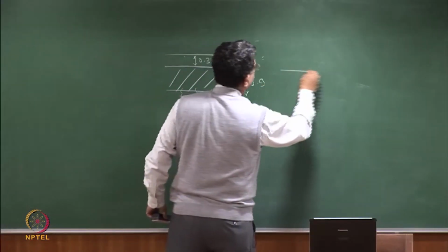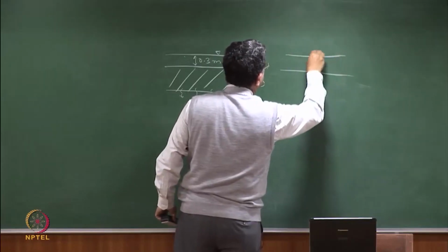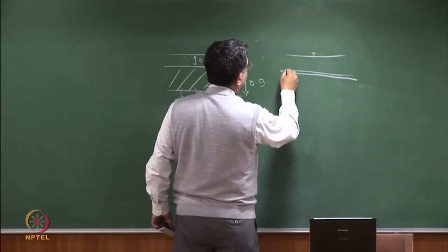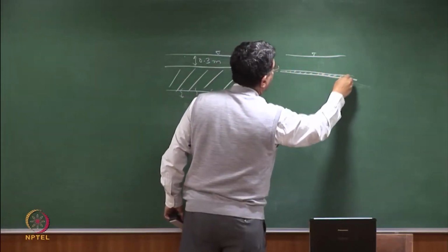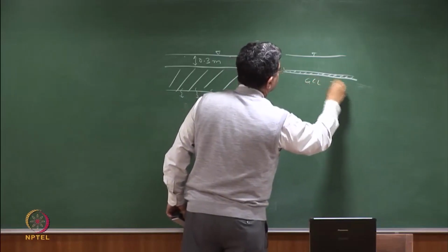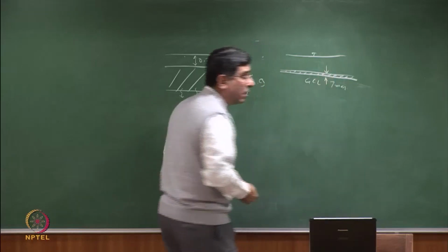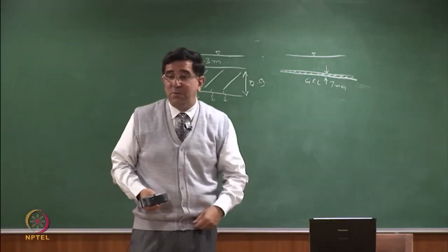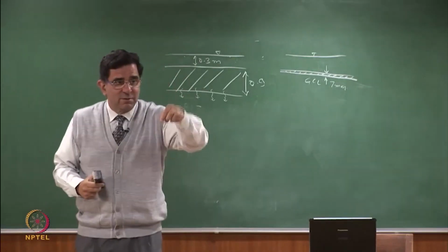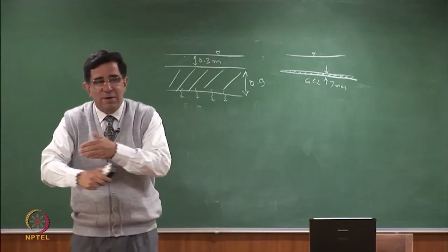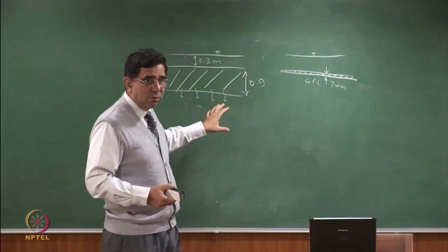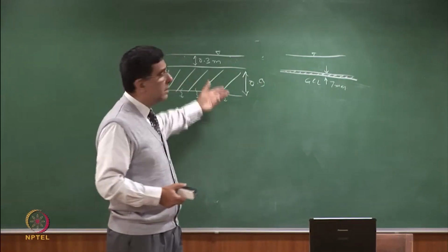We are comparing same leachate head, but now that is your seven millimeters. It's thicker than a geomembrane, which is 1.5 mm. But the GCL is supposed to be self-healing. So if you have a puncture, the bentonite will expand and heal itself. So we are going to now compare the Q through both of them, right? But this problem is presented.